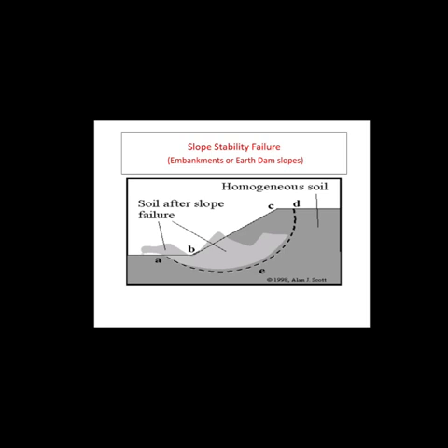Then why study the shear strength of soils? The study of the shear strength of soils is essential to establish the stability of various earth or earth retaining structures such as slopes, retaining walls, foundation bearing capacity, etc. The slide shows a man-made slope, or an embankment, or an earth dam slope.